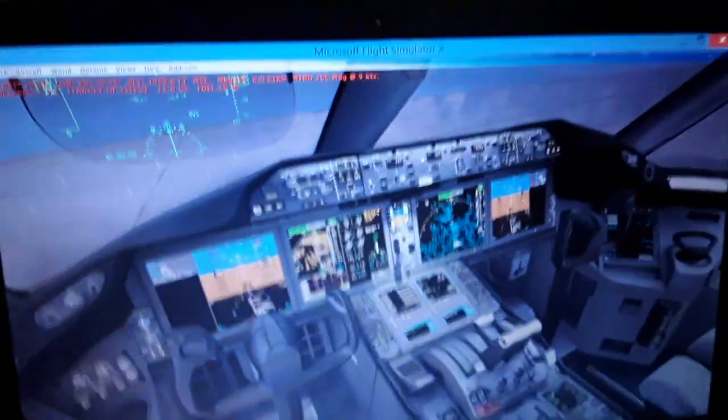Also, the aircraft flies with an airspeed 2 or 3 times faster than at sea level, so we have a difference of air intake from the front fans inside the engine. This creates a different fuel-air mixture request every second, so this is adjusted by the FADEC automatically every second. So the FADEC adjusts the fuel-air mixture automatically instead of doing it manually like on a turboprop aircraft. So you don't need to use the auxiliary engines on the aircraft, or you can anyway. Also with descent back to sea level, we have to do the vice versa. This is done automatically again by the FADEC.